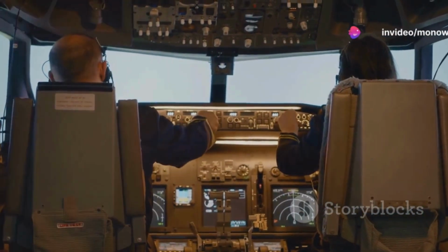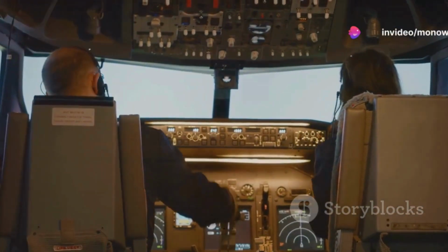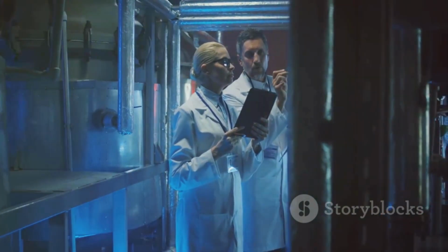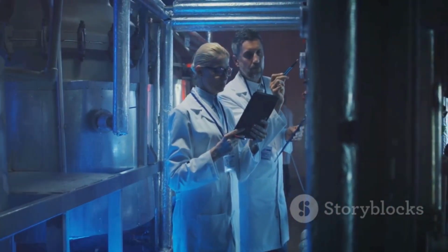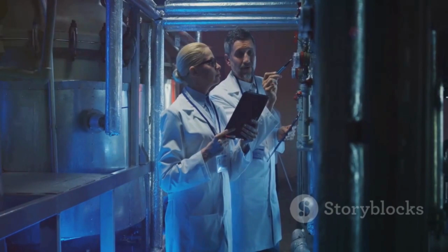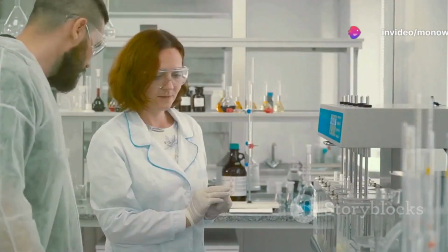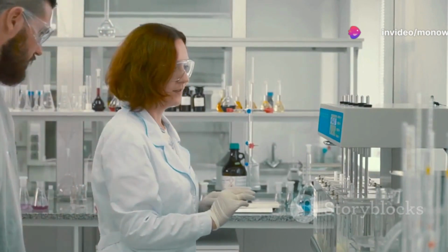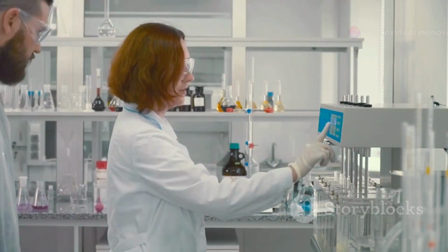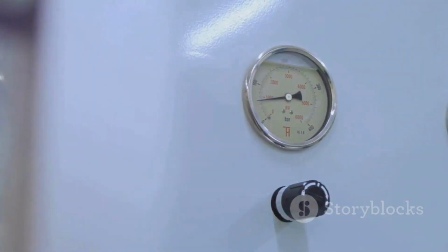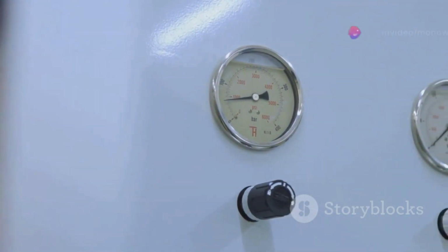That's where calibration comes in. Calibration is a meticulous process that involves preparation, adjustment, and verification. First, the device is prepared, ensuring it's clean, stable, and ready for calibration. Then it's adjusted to match a known reference standard, a device that's been calibrated to an extremely high degree of accuracy. Finally, the device is verified, comparing its readings against the reference standard to ensure they align.